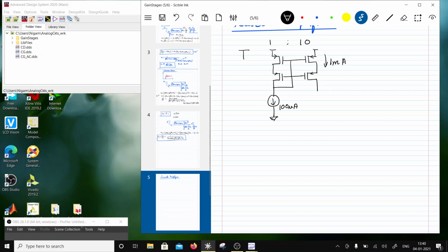Now we use another transistor which is twice the overdrive voltage, which means it is 1/4 the size of all these transistors, which is going to establish this voltage, right? If we keep the current same, then the twice overdrive is possible if I use 1/4 the size. So this is 1/4 the size, and this will cause the impedance looking in here to be GM RDS square.